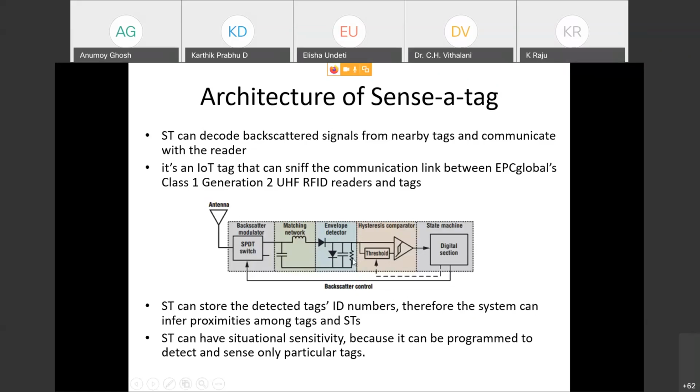The demodulation of amplitude modulation is an envelope detection technique. So from that envelope detection, after decoding that amplitude modulated signal, I will get the distance between my car and the other car. Suppose the dangerous distance is, say, 10 meters. Now your car and that car from which your tag is receiving the signal has come to a distance of 5 meters. From the envelope detector, you will decode that information.